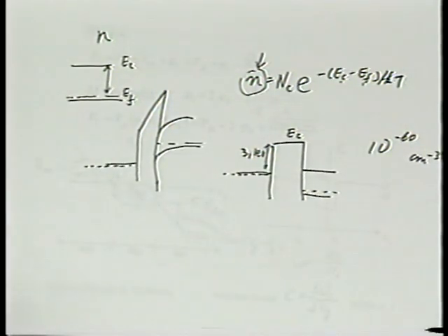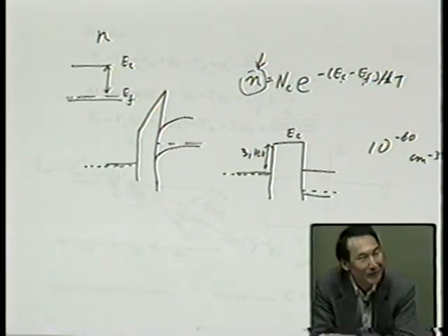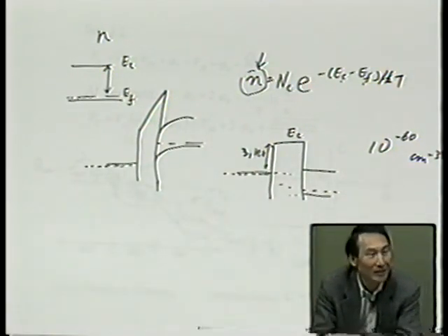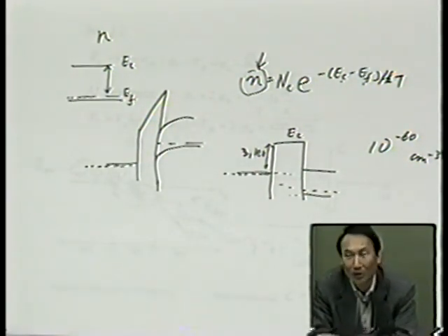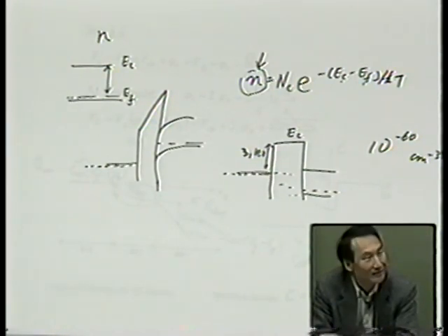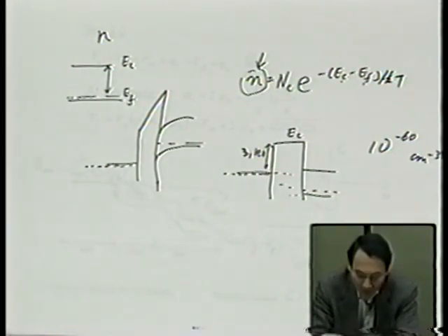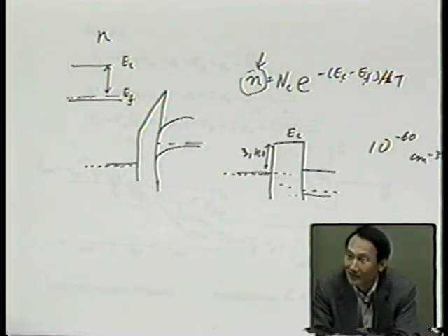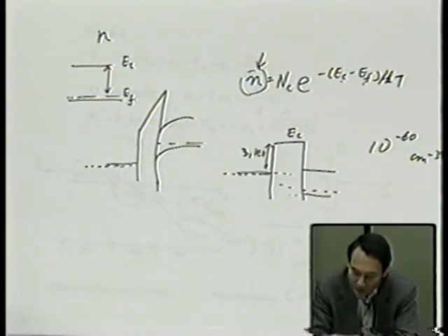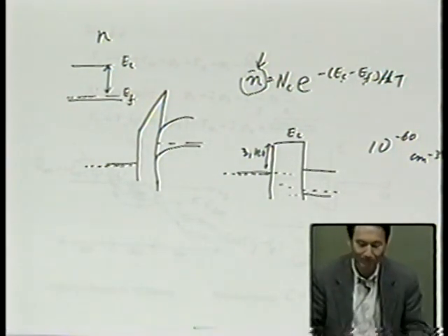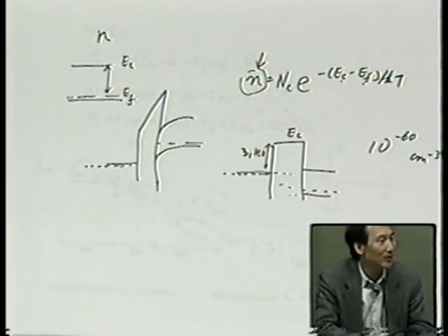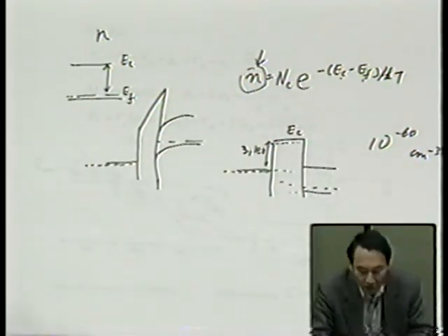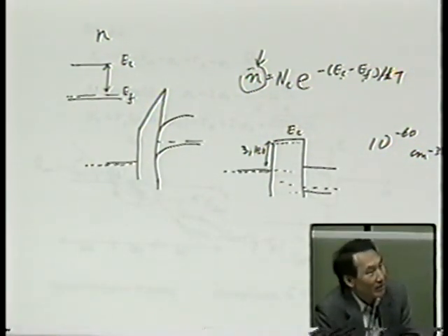Is there any meaning to this number? Obviously, it's a meaningless number. It really doesn't matter whether the Fermi level is here, here, or here. It makes no difference. That's why we don't talk about the Fermi level in the oxide. Put another way, wherever the Fermi level lies, it's acceptable. It doesn't contradict any relationship that has to be followed. That's why we don't have to worry about the Fermi level. If, however, there's a situation where you have to draw a Fermi level here, you have to really think about it. What does that mean? Does that make sense?